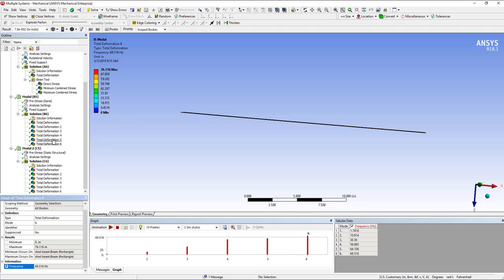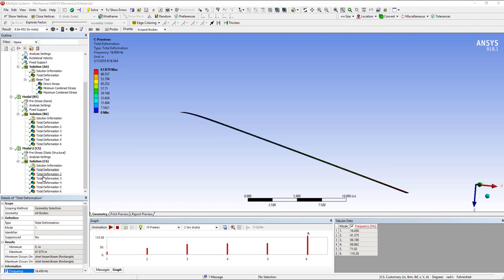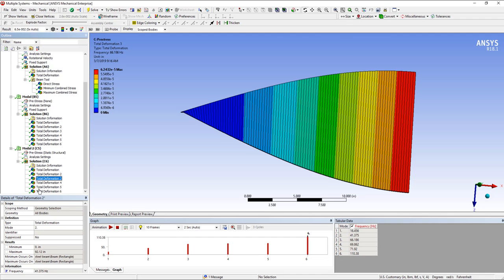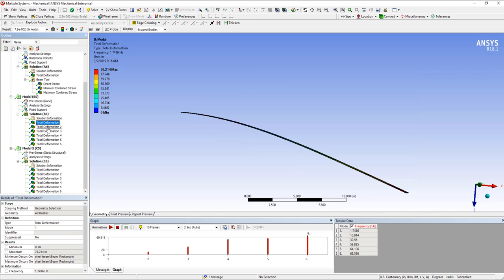I could go through this for some of the others, and then I could run a simulation to see how those frequencies varied with the speed. Okay, so I've made my pre-stress frequencies, all the frequencies down here, a parameter. No need to do that for the unprestressed, because that will not change as I change those values.